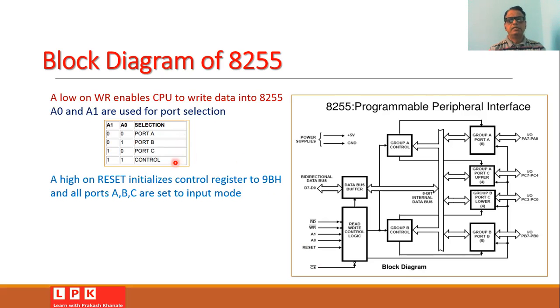Also, we have a reset pin, and a high on the reset pin will initialize the control register to 9B hexadecimal, and all the ports A, B, and C are set to the input mode.